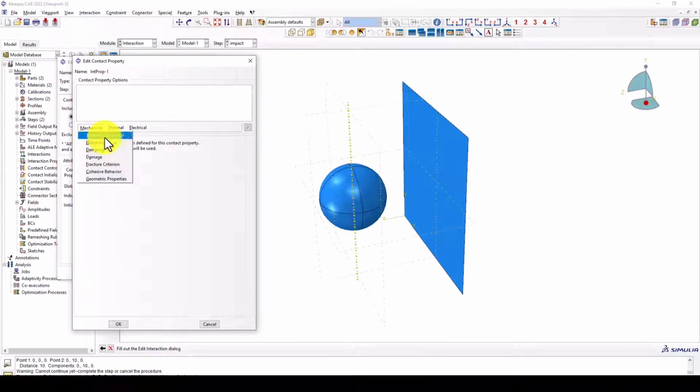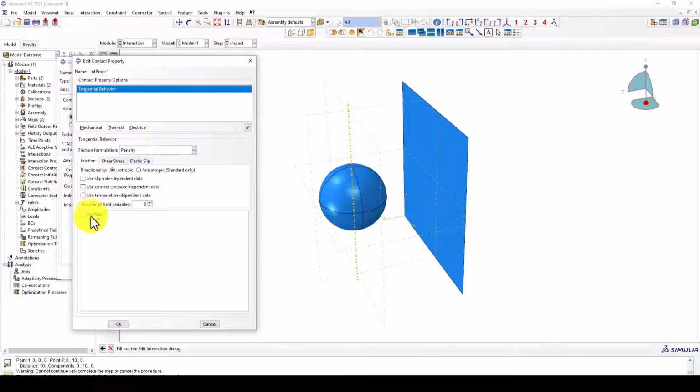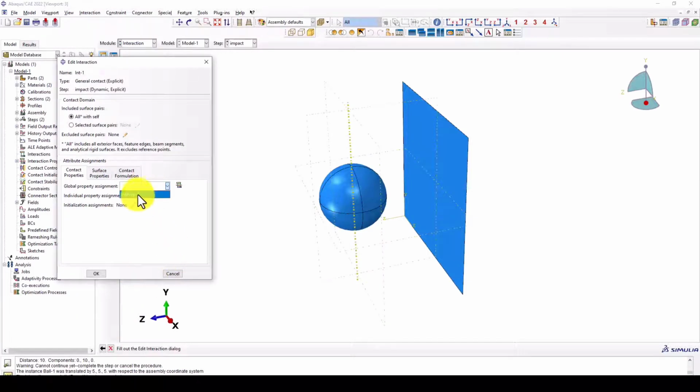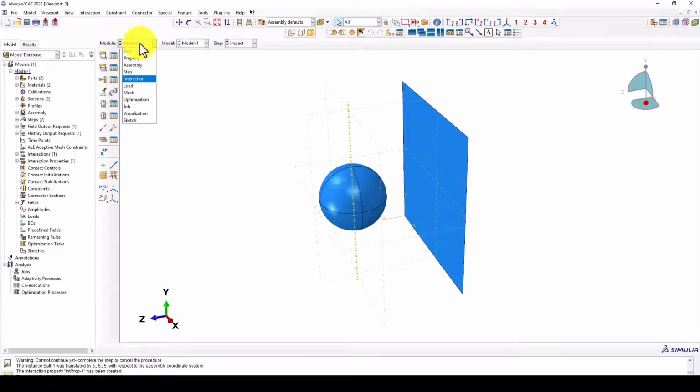There is an important distinction: a rigid body can participate fully in the dynamic contact problem. It doesn't necessarily mean that the entire simulation becomes a rigid-body-only simulation. For example, our ball can be rigid while the plate remains deformable. The ball transfers momentum and energy to the plate through contact, and that's when the rigid body dynamics come into the picture.